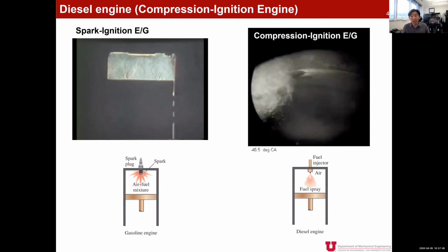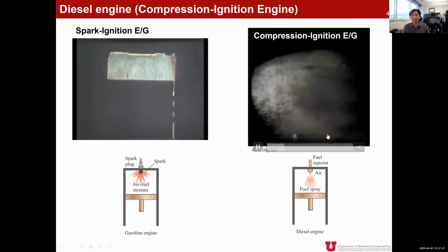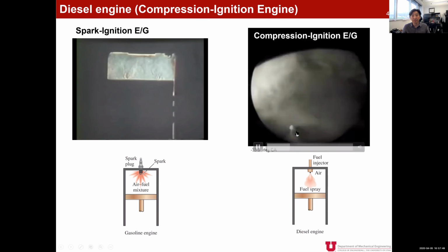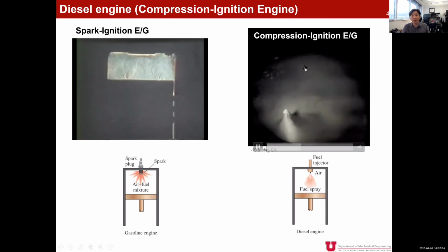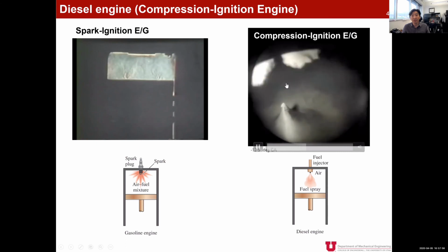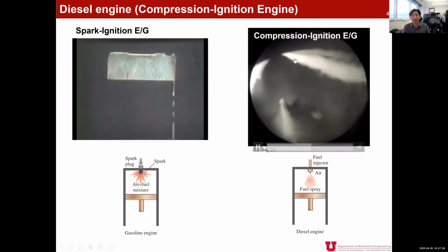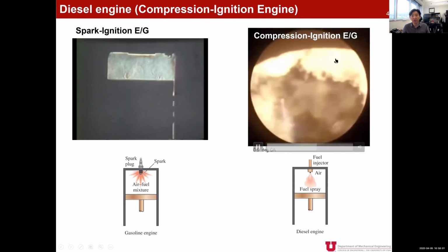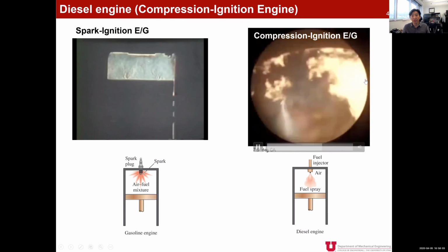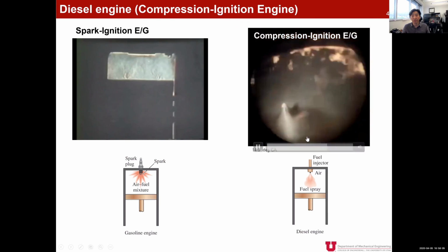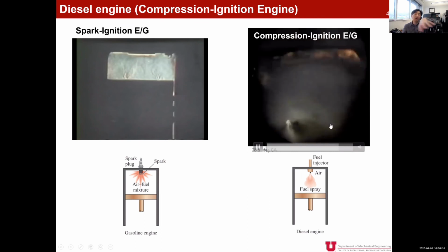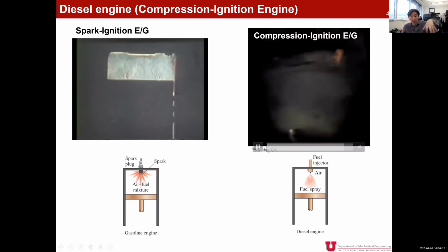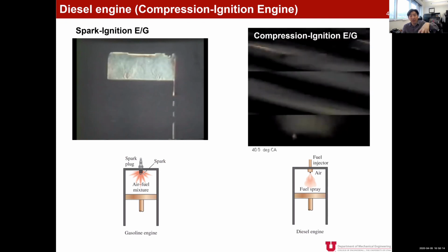And now you see the piston comes up. So that is the end of the compression. Now we have sprayed fuel. Now, yes, now the flame starts, following the sprayed direction of the fuel. And you also see swirling, or rotating, of the flame around the cylinder combustion space. That is how we see it.